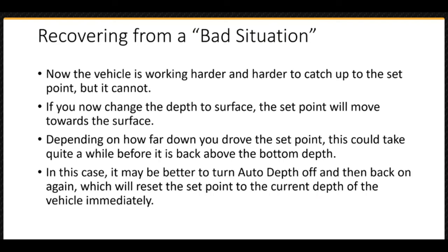Recovering from a bad situation. Now the vehicle is working harder and harder to catch up to the set point, but it cannot. If you now change the depth to surface, the set point will move towards the surface. Depending on how far down you drove the set point, this could take quite a while before it is back above the bottom depth. In this case, it may be better to turn auto depth off and then back on again, which will reset the set point to the current depth of the vehicle immediately.